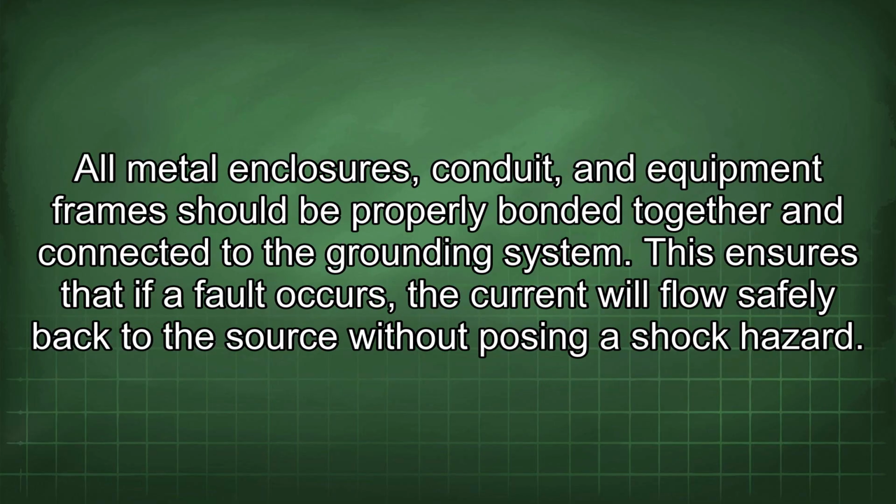All metal enclosures, conduit, and equipment frames should be properly bonded together and connected to the grounding system. This ensures that if a fault occurs, the current will flow safely back to the source without posing a shock hazard.